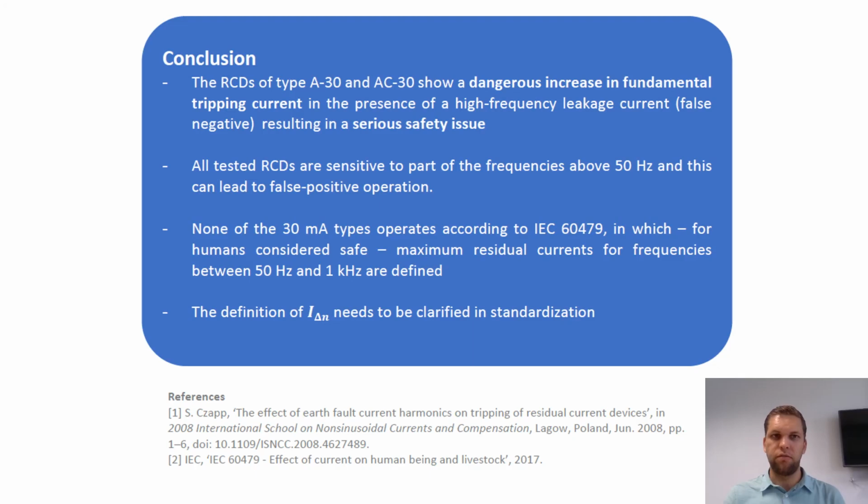To conclude, the RCDs of type A30 and AC30 show a dangerous increase in fundamental tripping current in the presence of a high frequency leakage current. So this is a false negative situation which results in a serious safety issue.